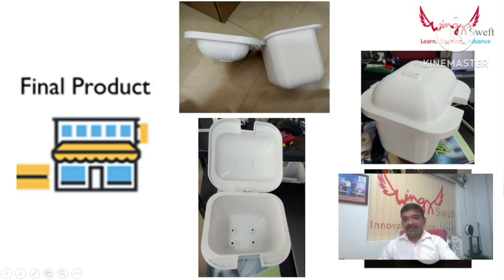Okay. Then these all are standard parts which are available on the market, and I need to fasten them here. So I have fastened them, and I checked all the fittings, everything. This is like a prototype. I have made a prototype before making a plastic mold for this. We checked all the interferences and the aesthetics, looks, everything in real life within a very little time. Then we confirmed everything is fine. If any adjustments or modifications were required, we made them within a small span of time, and we have done the die design as well as die manufacturing.